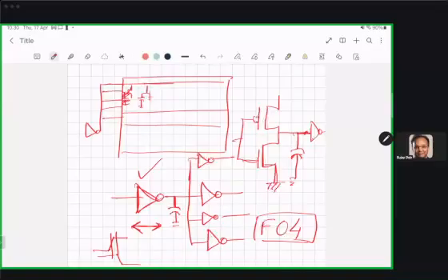So when you are driving hundreds of rows, your delay will be more compared to when you are driving 10 rows. So as you make your memory bigger and bigger, the memory becomes slower. The wire lengths become longer, the delays become larger. That's why you can have a big memory, but you can't read or write it very quickly.